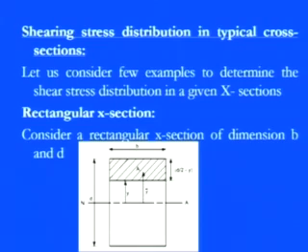So using that segment, if we have a segment, or we can say a strip, which is at a distance of y from the neutral axis, the centroid of the strip is located somewhere, and the distance between the centroid of this strip and the neutral axis of this rectangular section is y bar. Here you can clearly visualize the difference between y and y bar, and this is the real difference used in shearing stresses.